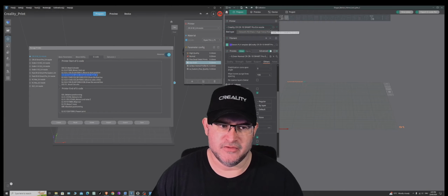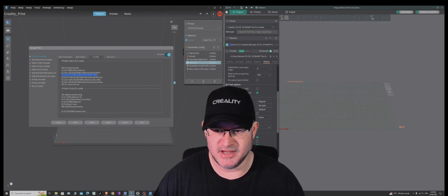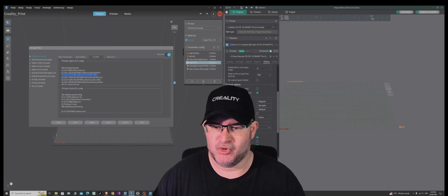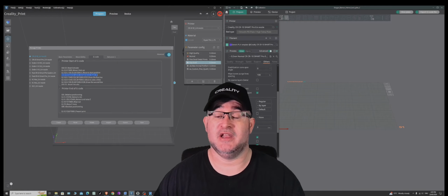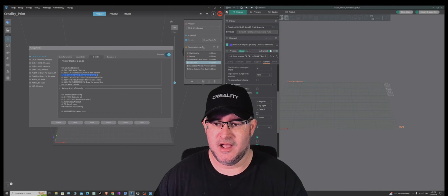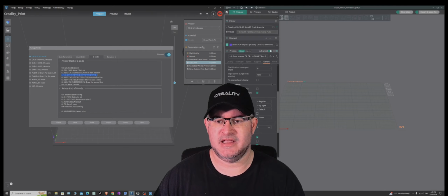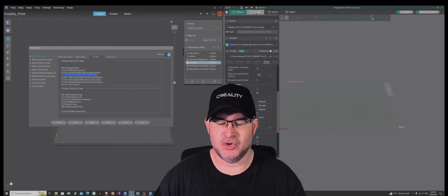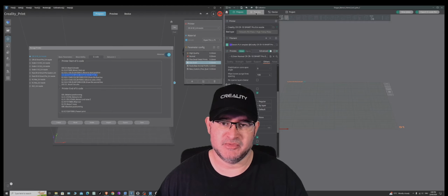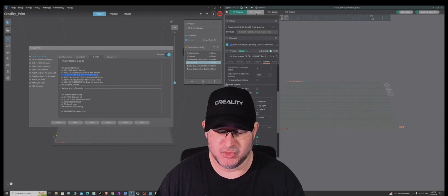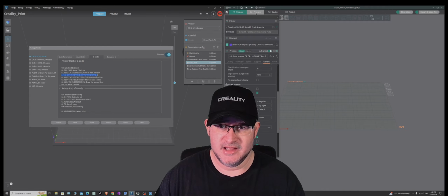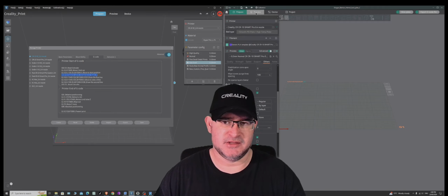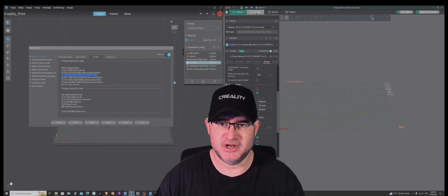And also you'll find to cross-reference the G-code to make sure it matches your slicer with any parameters that slicer needs to recognize certain temperatures between the nozzle, the bed clearances, and the nozzle temperature before starting a print and during as well, is also check within your manufacturer slicer. So simply open up whether it's Prusa, you've got a Prusa printer, you've got an Elegoo printer, Anycubic, or even the profiles that have automatically been included in, say, Cura, for instance.